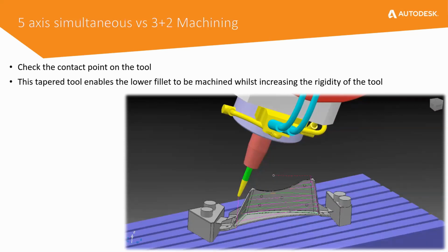So it efficiently tilts its tool axis at the corner radius and with the adjacent surfaces of the part. At the same time, if you use 3+2 machining here, only the tool edge will contact the part, so we have to reduce the depth of cut, which obviously increases the cycle time, and there will not be any smooth transition at the corner radius of the part.